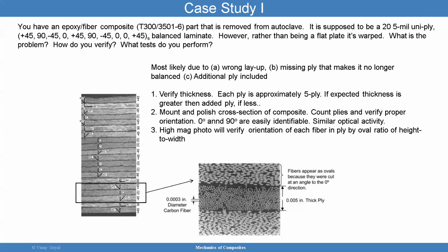So that's one approach you can use for case study number 1 as an example. For those that are watching this, there's an error that I put here on purpose. Here it was supposed to be symmetric with the S. That's what symmetric means. I hope you caught it. The error is that it's supposed to be mirrored by 45, and you can see here that it's not mirrored by 45 because there's a minus 45. So for it to be perfectly symmetric, you need to have these at 45 as well, and that says minus 45. So that's an error that was also caught by this cross-sectional work that was done.